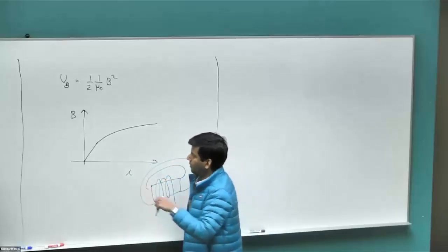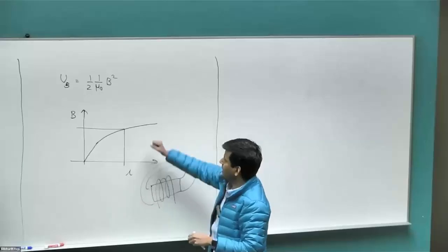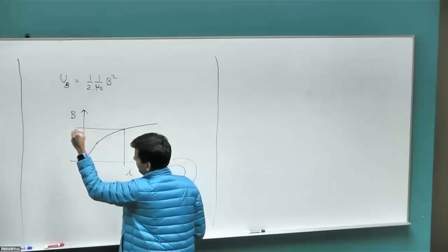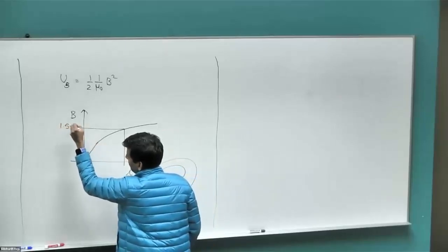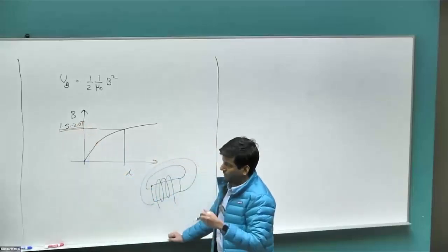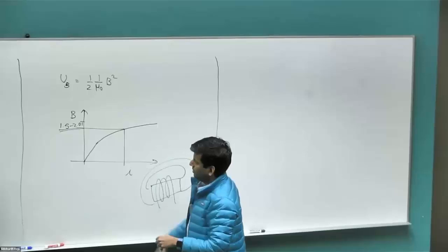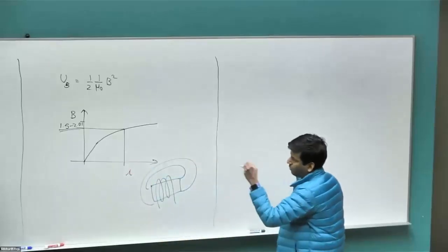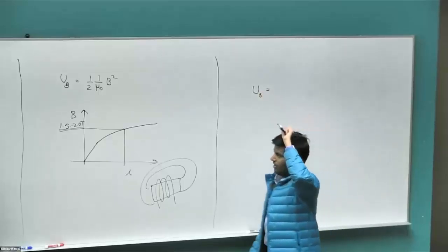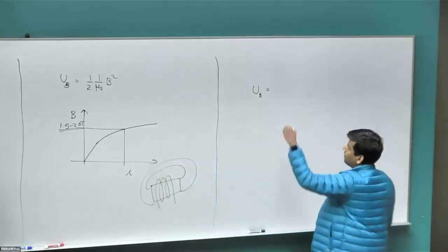Right? So optimally you would operate it just in the region of saturation, but not deep into saturation. Typically, when you have an iron core, silicon steel in particular made for machines, you wouldn't try to operate it at more than 1.5 to 2 Tesla at the best case, right? So let's take the lower limit, just to give a fair competition to whatever energy density the electric field came out to. So let's start with 1.5 Tesla. That's the maximum B field we are ever going to be able to operate our motor in, above which it doesn't make much sense. It's not rewarding enough.